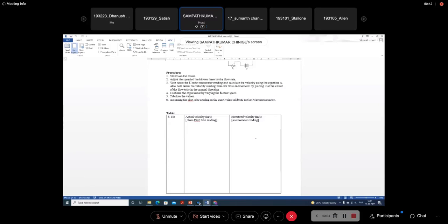So before using that, you have a standard setup where, if you want 2 meter cube per second volume flow rate, it will directly provide that. If you want 3, a well controlled amount of fluid will come out. So you can put this anemometer at the end and calibrate what is the exact value of the flow, what it is showing, and from that you get a curve. From that curve you will try to find out the constant values.